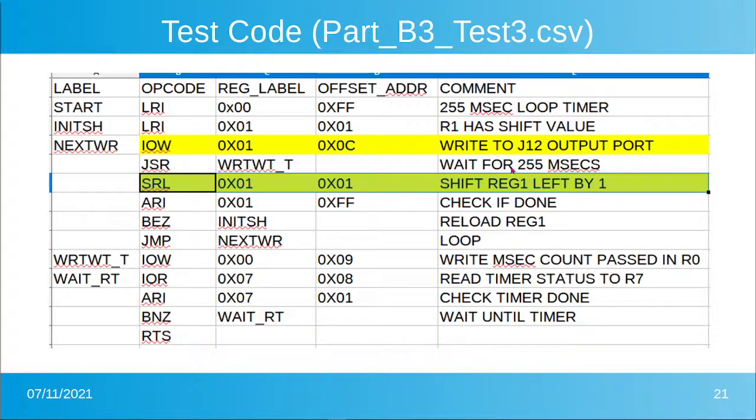Then we'll wait for that time that's inside the 0 in this wait subroutine. We're reusing the wait routine we wrote for the other example codes. It's a jump subroutine with a return subroutine at the end. Then to check if we're done, we'll first do the shift, and so this will be testing if the shift worked. We'll shift left by 1. Remember, we've hard coded this value, but we have to set it in here, otherwise the assembler will say, hey, I don't implement that yet.